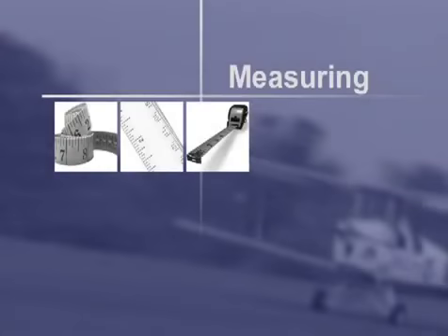If you've weighed a lot of different small aircraft, in this one in particular, you look at the weight of the tail, and 51.75 pounds is quite common. You'll have a light aircraft that might have anywhere from 40 to 65 pounds for a tail wheel weight. That's fairly common. So we got the weights, we wrote them down.